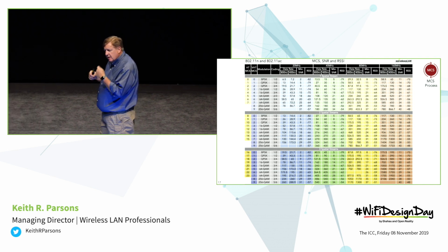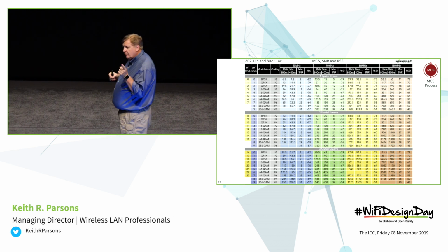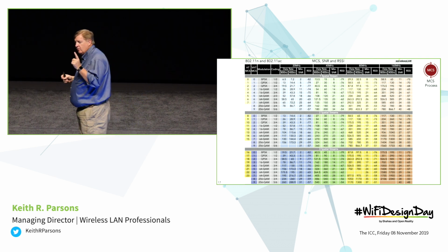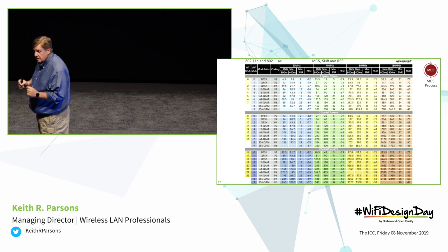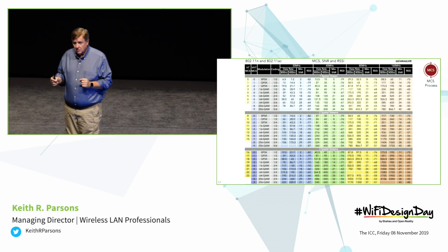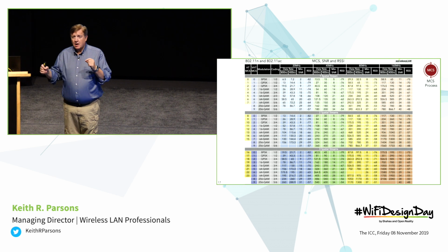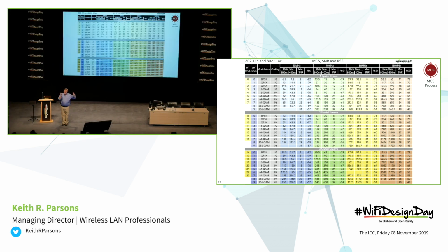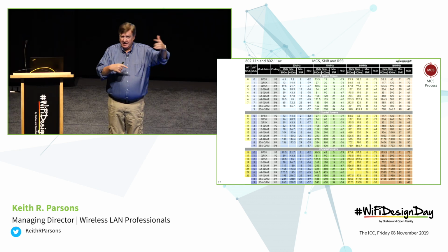The client's sitting here thinking, it could have been because the radio frequency was congested. That could be an issue. Okay, so it says, I will take my game where I listen before I talk and then I grab a random number. My random pool was not big enough. I will make a bigger random pool in case I was bumping into someone else.